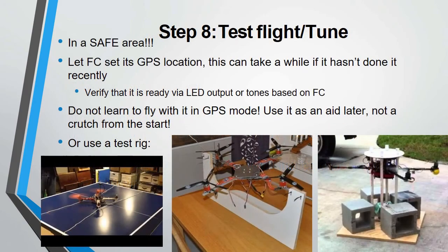Step is test flight tune. Now in a safe area, let the FC set its GPS location. This can take a while if it hasn't done it recently. Verify that it is ready via LED output and tones based on FC.